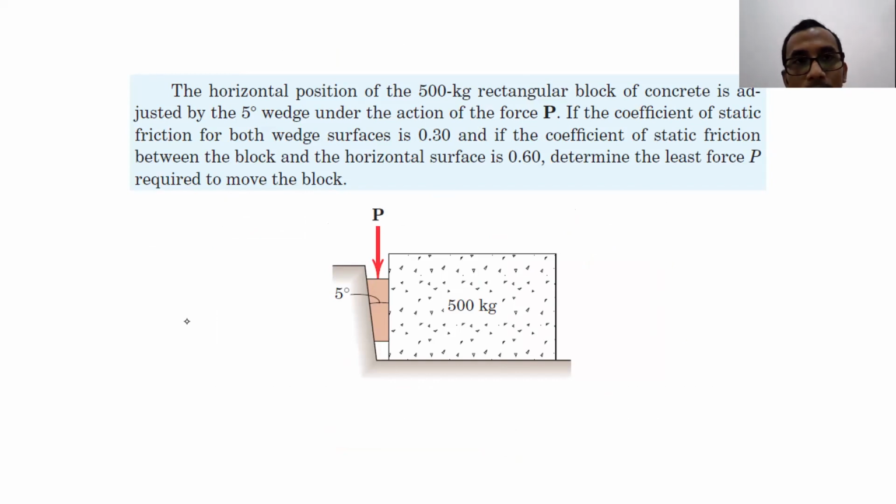Nuki, do you have any question? Sir, for the least force, we just use equilibrium to solve P, right? Oh yes, we just need to use equilibrium. And remember, when we discuss the wedge, it's always a point force, so there will be no sigma moment there.